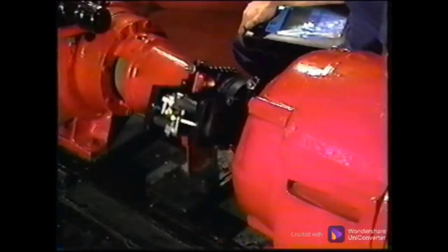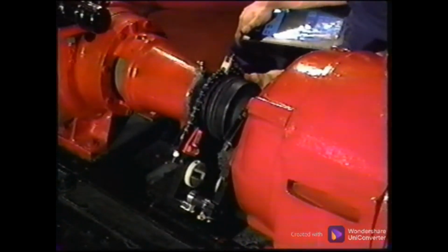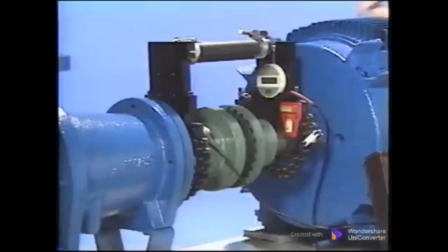One benefit of the electromechanical system is that it doesn't require a full 360-degree swing in order to calculate the machine moves. At least 3 readings are required, so a minimum rotation is 180 degrees. The 4th value is then calculated from the data validity rule.